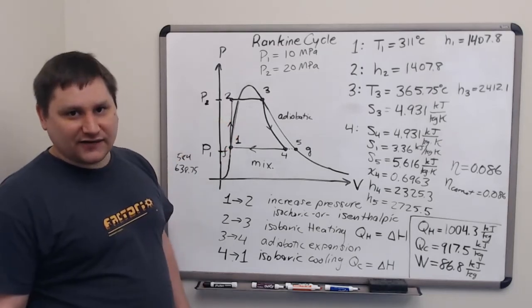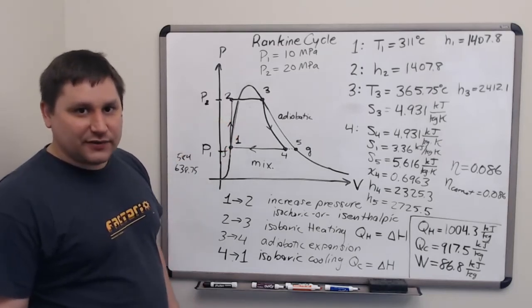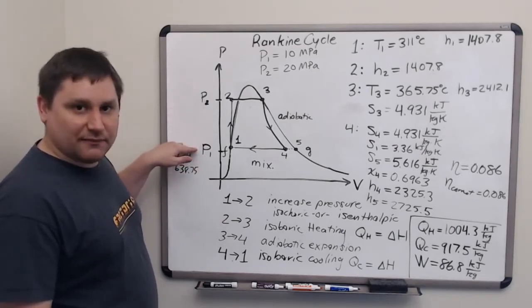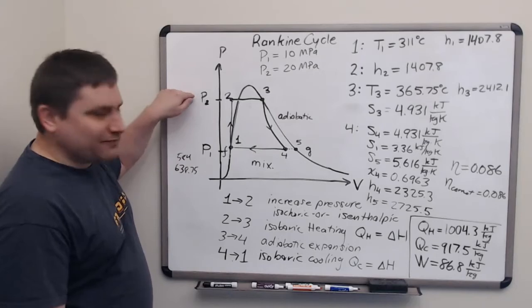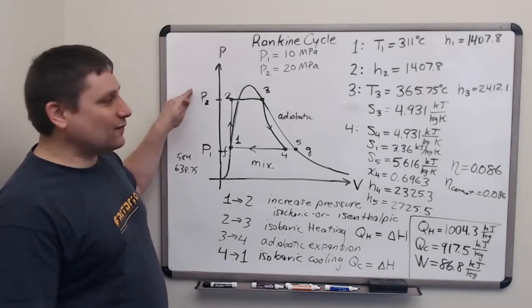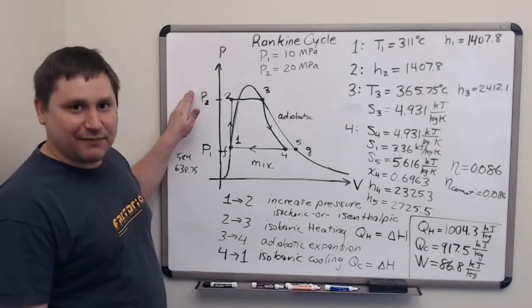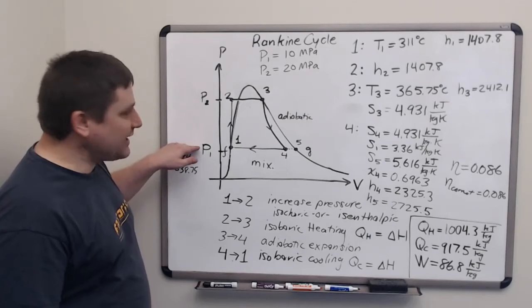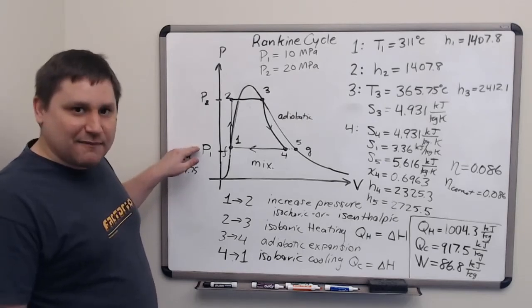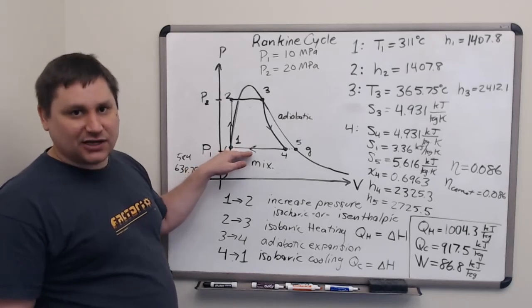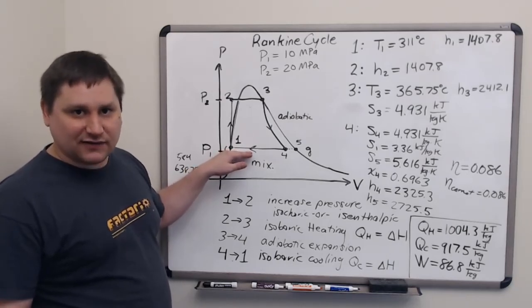If we want to make our cycle more efficient overall, we would need to choose either a higher top pressure or a lower minimum pressure. Making the top pressure higher comes with certain risks. Boilers were well known to be dangerous in the past for having a risk of explosion. But we can also get a gain in efficiency simply by making the cold side of our cycle at a low pressure, sometimes even lower than atmospheric pressure, by using sealed pipes.